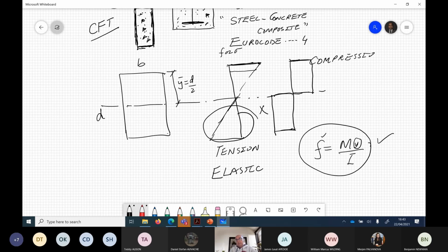It means that material goes into plastic range. If I talk about steel or any material which shows some plasticity, that will be drawn like this. So these are two extremes. Now this is a typical one for steel, but for steel, it is strong in compression, it is strong in tension as well. So I can draw it like this.